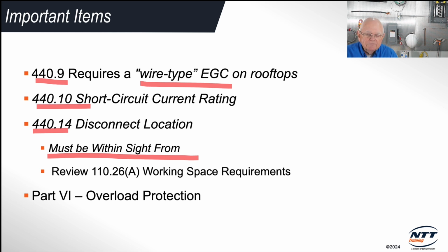Also, keep in mind 110.26(A), your working space requirements. So it covers the depth of the working space based on a table from your equipment, from your disconnect in this case, back to what's behind you. There are minimum depth requirements there. And so you're looking at 3 feet, maybe 3 feet 6 inches in some cases. And it also covers the width of your working space, where you've got to have 30 inches, shoulder room as I call it, to get in there and work on that disconnect or that equipment.